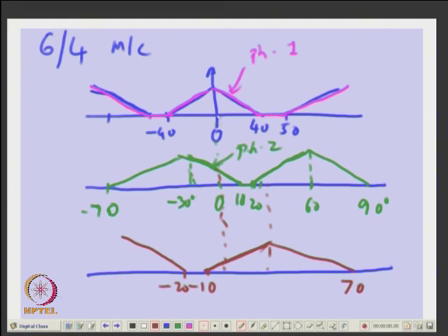Okay, each one is 40 degrees, minus 20 it goes to minus 60 or something. Minus 100. Okay, I have written broadly the inductance profile of 3 phases, phase 1, phase 2, phase 3. And when do you excite each of the phases? What instant? What is the instant you would like to excite? What will be the current waveform you would like to give ideally?